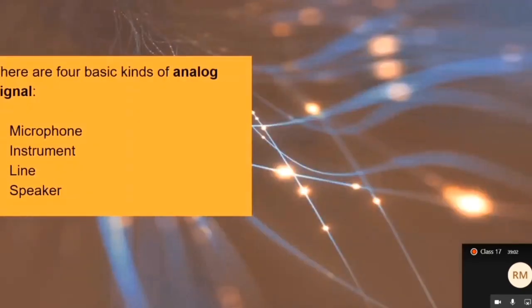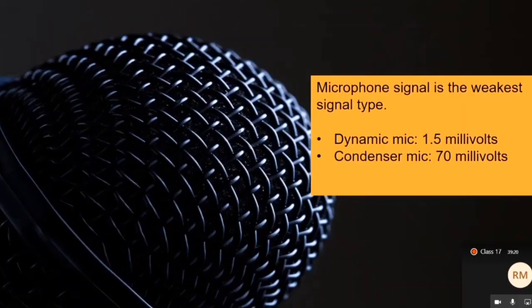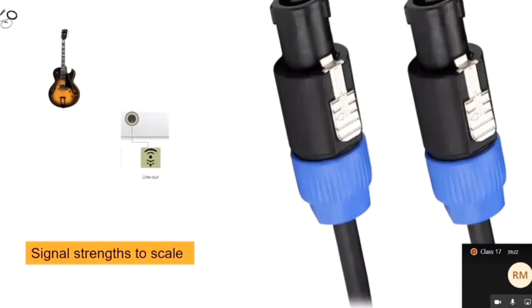If you're going to be a producer, a recording engineer, or a live sound engineer, you're going to encounter analog signals. There's no way around it. And in this realm, there are four analog signals: microphone, instrument, line, and speaker. They are only different insofar as the intensity of the electricity that they carry. They're all carrying analog audio. And this picture shows you the difference in voltage.